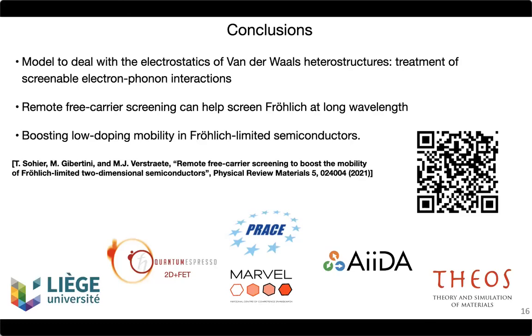I think screening from the gates. Yeah, screening from the gates is something that in the transistor community has been taken into account. But there's a proximity here that is allowed by 2D materials that really enhances the effect. Here I've not clearly shown it, but if you put more layers of BN in between the gallium selenide and the graphene, if you increase the distance, this effect is going to decrease as well.